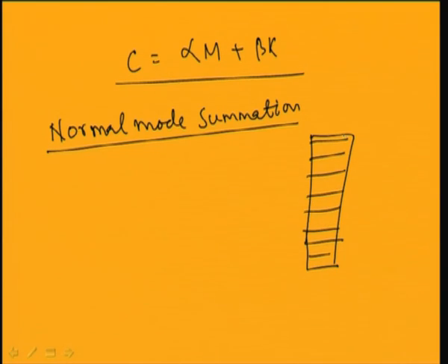Let us take a 10-storied building when it is subjected to an earthquake, or an excitation at the base, or from the support there is some excitation, and let us assume that it is limited to the first 3 mode frequencies only. So in this case one can write the equation of motion using the mass matrix. If it is a 10-story building, then it is 10×10.